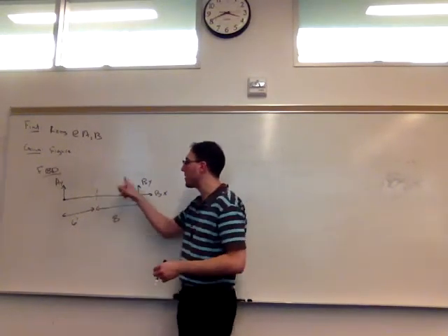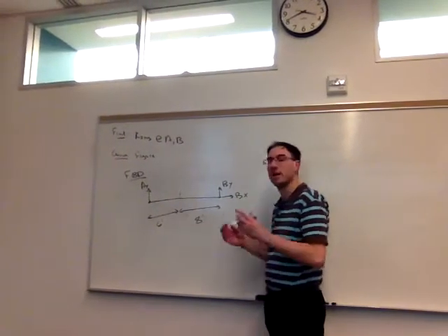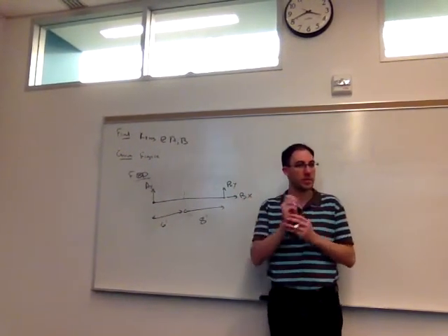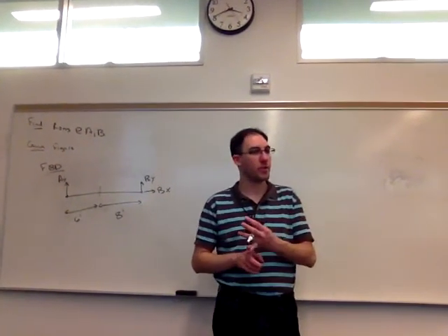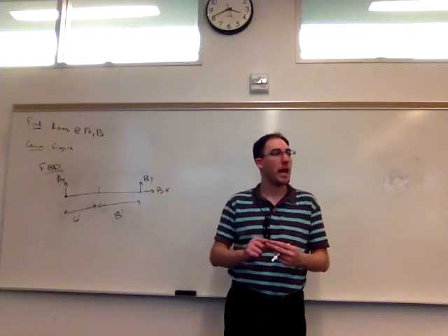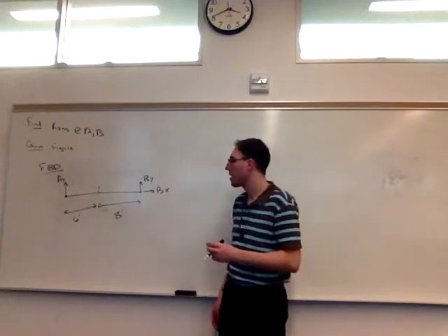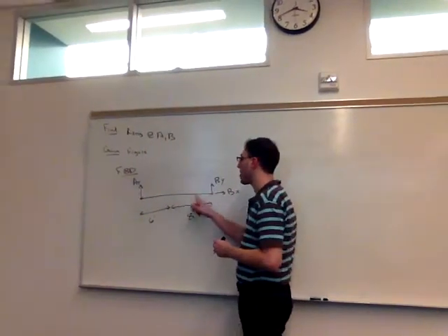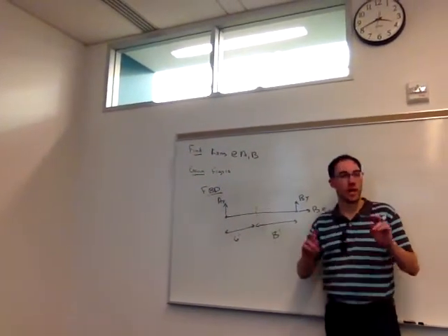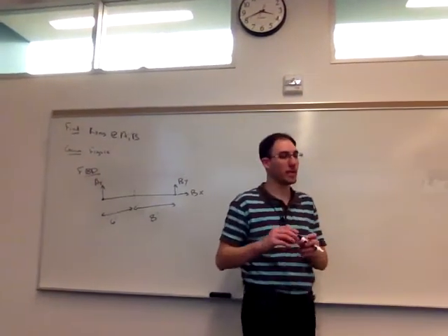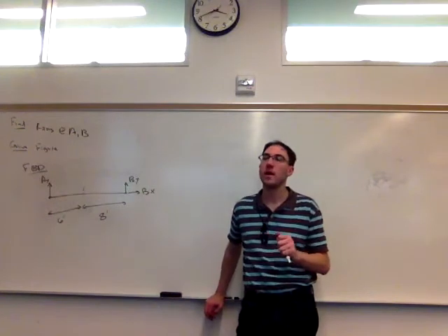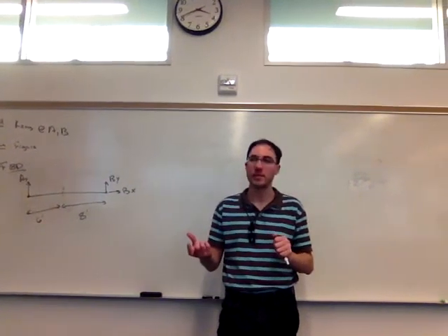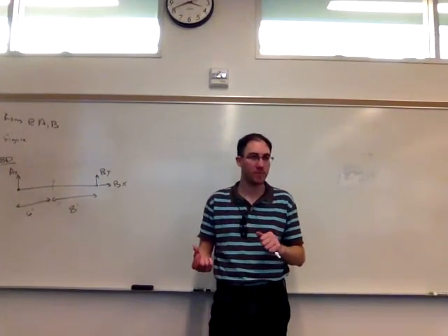So I can break this down into two different shapes and simplify each of them into a single load at a single point. But I have to find for each of those shapes what that load should be and where I should locate it. Let's look at the rectangular part first. The height of the shape, which is equal in this case to the intensity, is 150 pounds per foot. And this shape has a width we can consider of 8 feet.